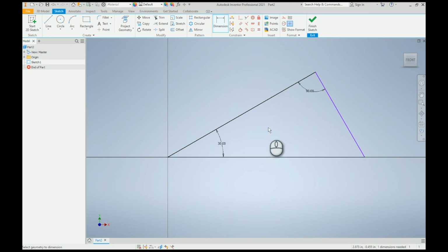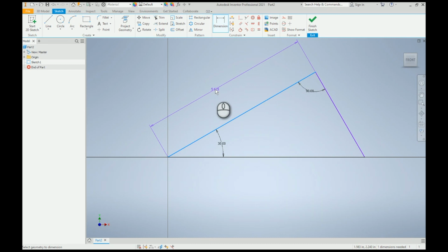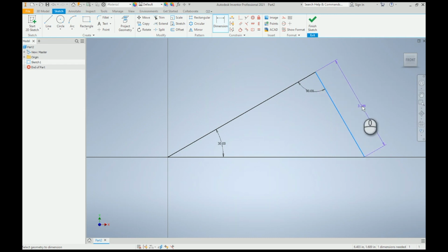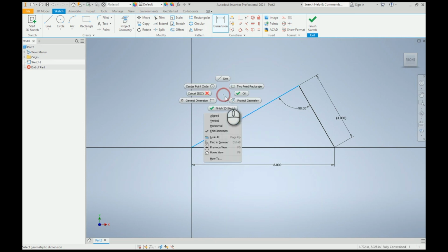Now, we can fix one of the dimensions of the mechanism. The others will be determined by it. We can design by entering the Geneva wheel radius, or we can design by entering the crank wheel arm distance. Let's design it by entering the distance between centers, in this case 8 inches. As we can see, the other dimensions cannot be changed, being determined by the distance between centers.